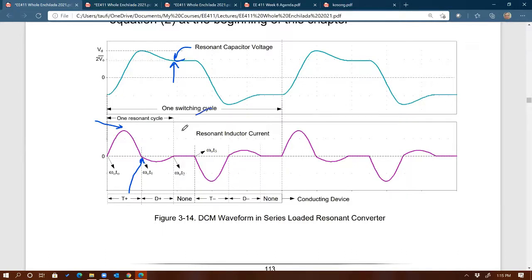So focus on the turn off right there. Junction capacitance? Well, because of the reverse recovery time, right? Remember reverse recovery time of a diode? So if you look at the way the diode turns off, look at what current the diode turns off at. It turns off at 0 amps, exactly. So we're not forcing the diode to turn off.